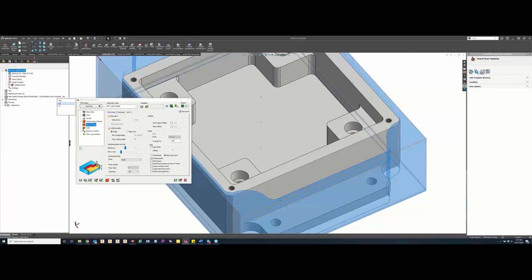Now, I think Greg talked about this just a little bit, but what this will do here is, even though I left 0.3 millimeters on there, if that's too much material for that tool to come in, it's still going to come and do the D-slot trochoidal movement in the corner to get that material out of there. So it's not taking that full 0.3 millimeter and over-engaging the end mill at that point. So, okay, we will go ahead and simulate that.